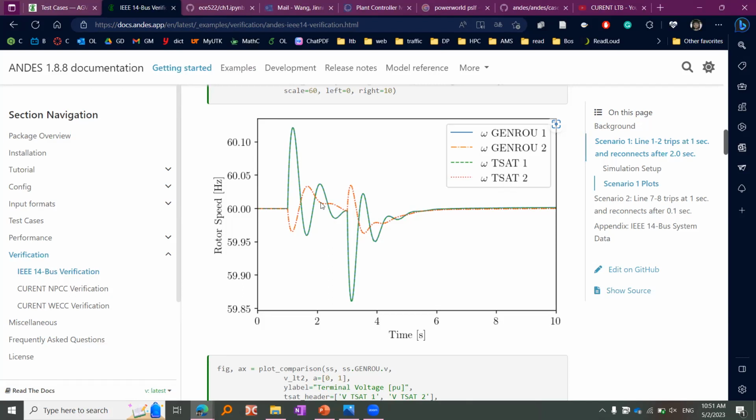One of them has to do with line faults or any sort of fault to the system. If the voltage drops below a certain level, the load model has to change because you can't use constant power. Typically below 0.7, they turn the load into an impedance, but it's not clear that each software does it the same way. It's buried inside the code as some sort of trick, and I don't even think you can change it.